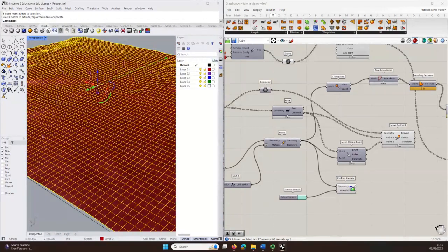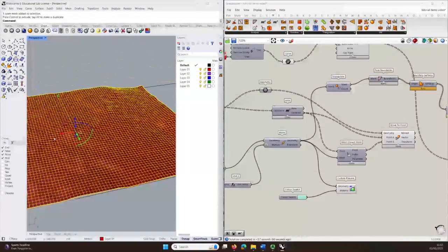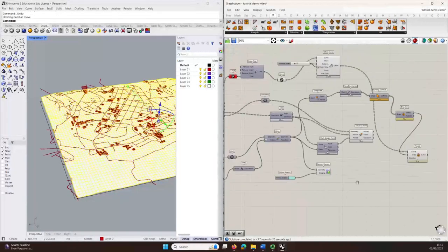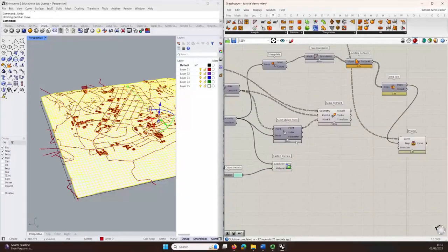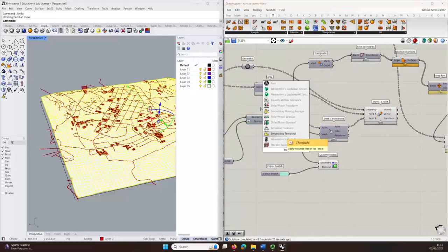So if I wanted to cut my roads or something in it, or I had some water features I wanted to import, that's all I can do. I'll just go back so it's in the right place. And the other thing I can do, instead of just having the mesh as a simple plane, is, I think it's called thicken mesh.